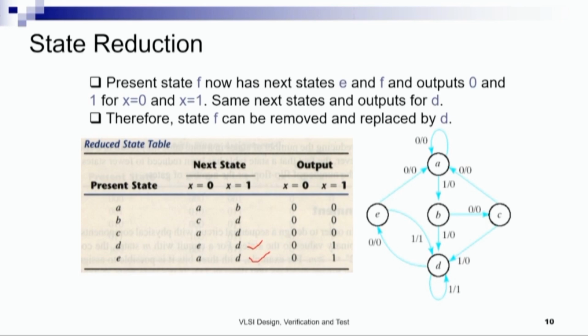We finally obtain this realization of the FSM. It is a reduced FSM. The original FSM contains 7 states. The changed FSM now contains 5 states. However, we will see that for all sequences of inputs, it is going to produce the same sequences of outputs, and hence the input-output behavior of both these FSMs is identical.